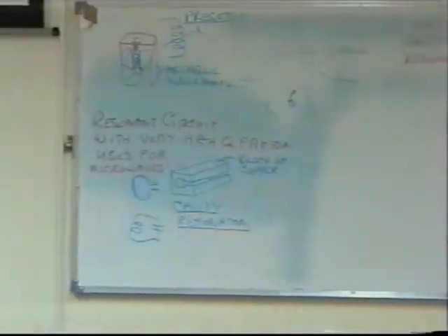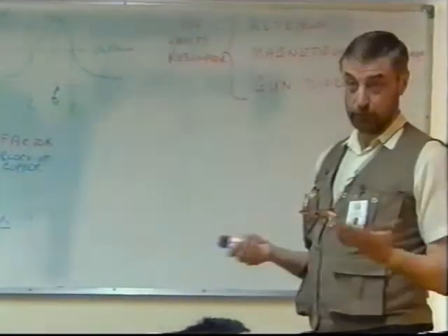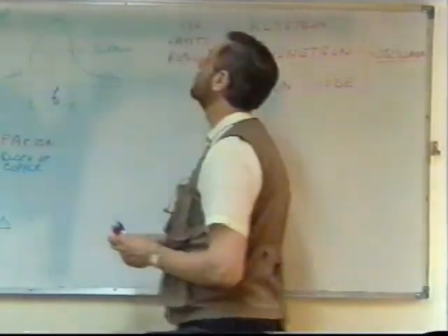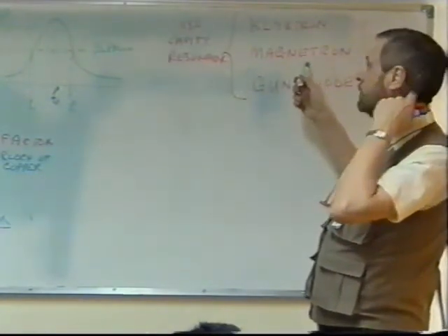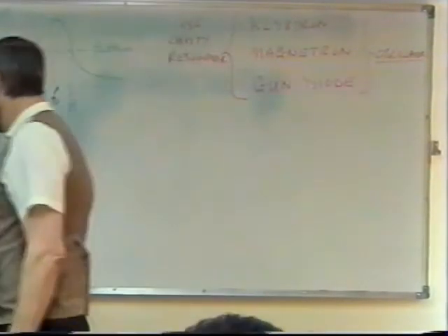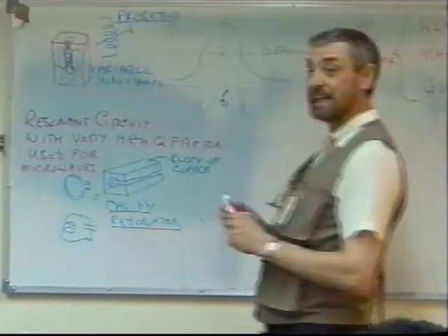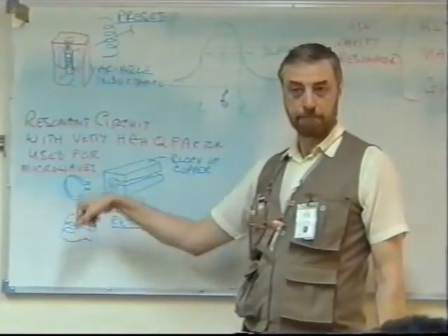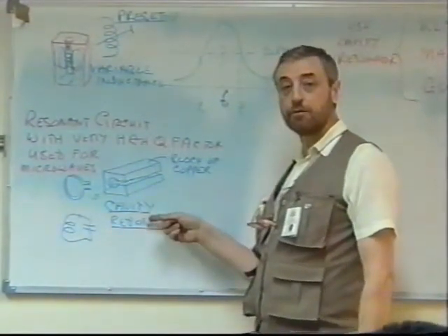But isn't there supposed to be a wire? Well, you mean how do we take the output? The output is taken usually by a little loop of wire connected inside the cavity to an output device here. It acts like a little radiating antenna. It picks up the energy here and radiates it out here. The power is connected to the cathode and the anode.